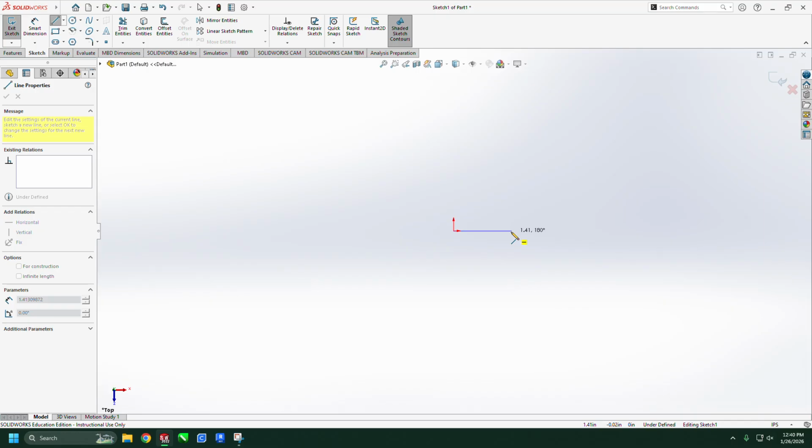So I'll left click to finish this line. Notice I want to be straight across. When I left click, it starts my next one. Now, I should be able to just go straight up. You'll see once I get to 90 degrees, it'll snap to that location. I left click again, and I keep going. Now, at any time if you mess up, just hit escape on your keyboard, and it will exit you out of draw mode. So once I get straight above my starting point, it'll show me a dashed line.